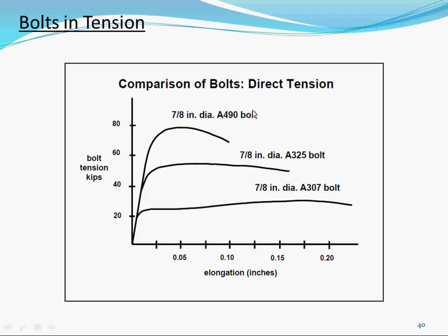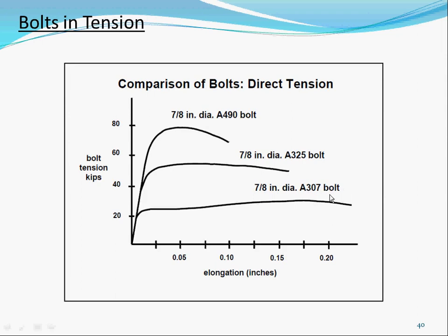So we're using this A490 and A325. The A307, we are using it, but only at the beam, the nailer connection on the top: the bolt from the wood to the steel beam top nailer. The Fy is about 65. Yep, that's right. So this is a lower Fy.